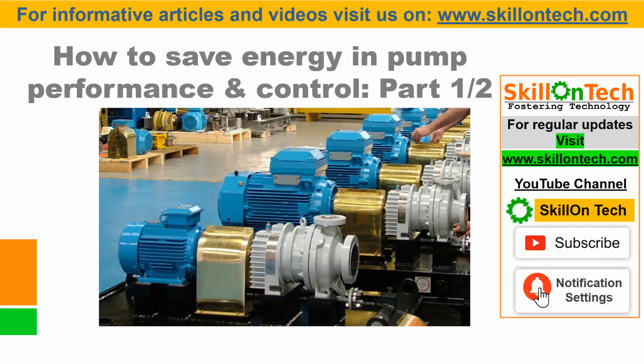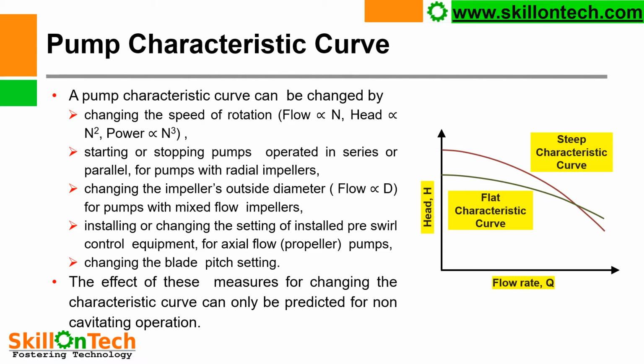Today I am presenting a video on how to save energy in pump performance and control. Pump characteristics curve. You can see a picture where the pump characteristics curve is shown. Head is on the y-axis and flow is on the x-axis. Two curves are shown: one is a steep characteristics curve and the other is a flat characteristics curve.